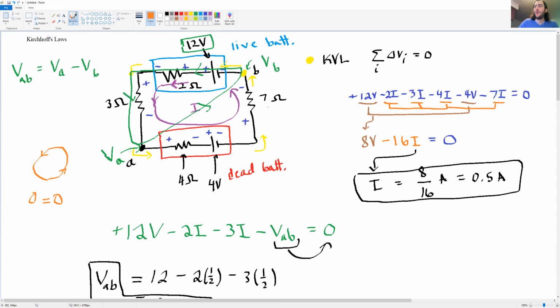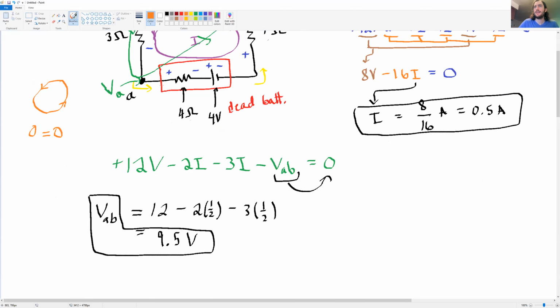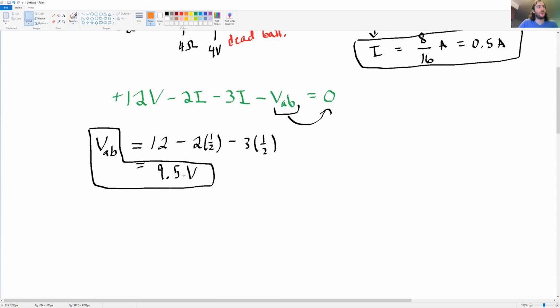helpful, right? But if we want to know VA minus VB, then we can draw this kind of a path here where we cut through the circuit and connect from the point A to the point B, and then we assume, of course, that there is a potential difference there. There's a potential at A, there's a potential at B. And so if I want VA minus VB, I should go from A to B and assume that that's a drop, okay? So I've dropped from A to B there to get VA minus VB. So that's the idea there, and that answers part B of our question.